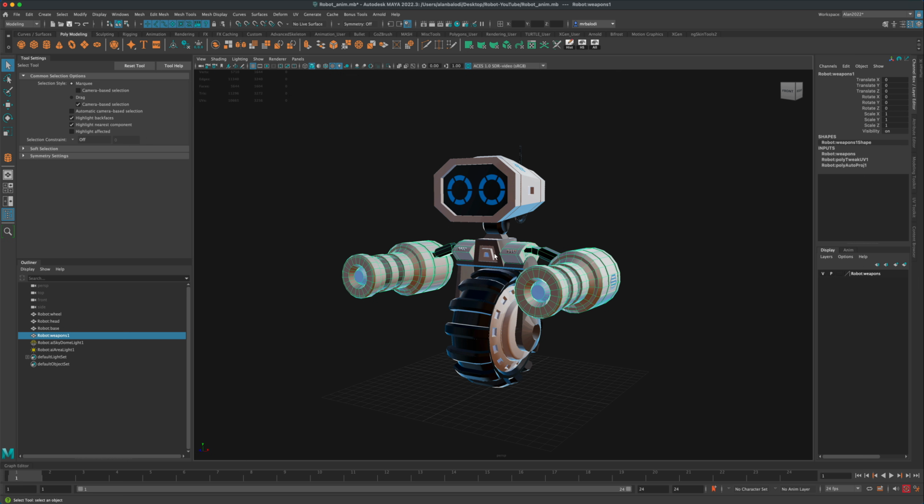So as I click on each one of these pieces, I can see that some have reset values and some do not. So make sure that every single one of them is set to 0, right? All of your elements. So that's super important. And before you do any animation, I strongly suggest you clear history on each piece as well.